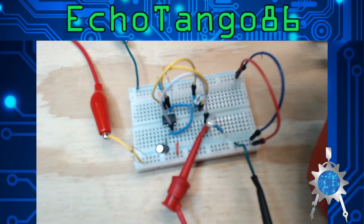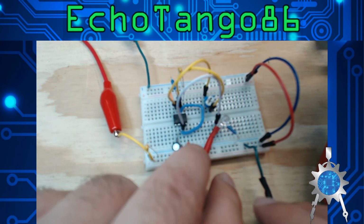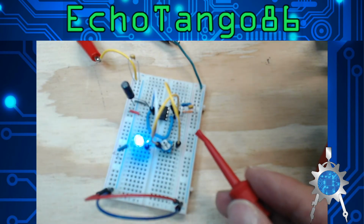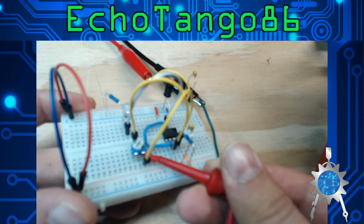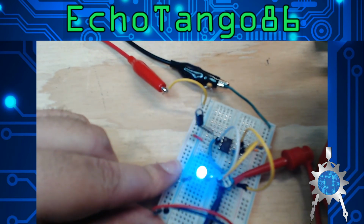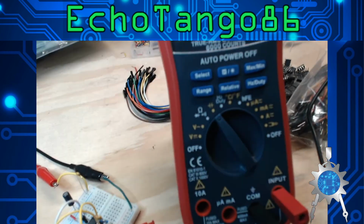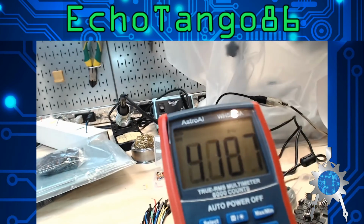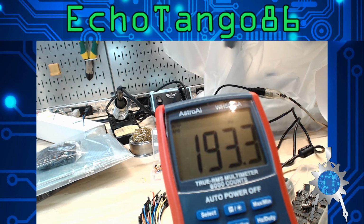Well, you know, I don't know what it is because I haven't really measured it. Now, we should try to check what the resistance value of it is. So what we'll do is pull off our leads here. The way we test the resistance is we hook it up to the end of one, and then hook it up to the other side. And then we switch it to the ohm symbol. Oh, you have to have it kind of hooked up. We're not running the voltage through it, because that is messing it all sorts of up.